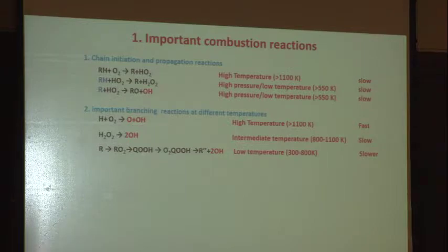Okay? And then, as I said in the last class, the peroxide decomposition reaction happens at 800 Kelvin to 1100 and is quite slow. And energetic plasma can always win against this reaction. So if you find that your problem, mostly an ignition problem, is below 1100 Kelvin, then plasma has great potential to enhance the ignition process.